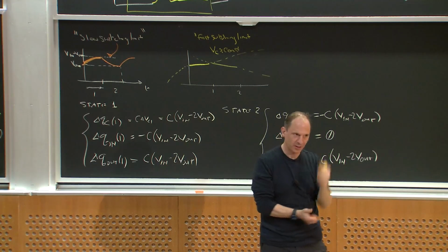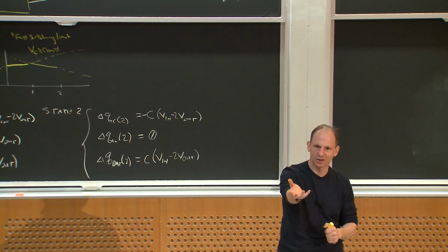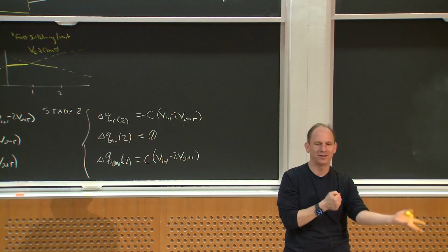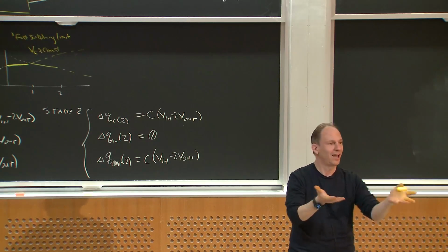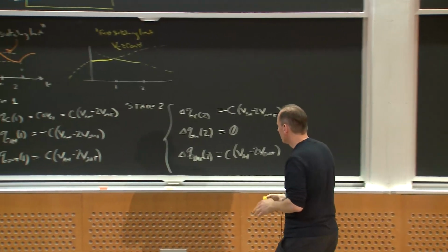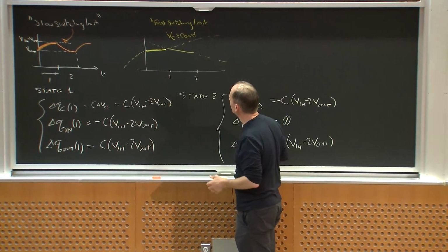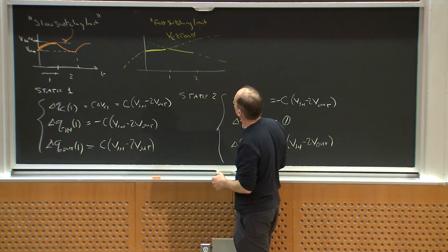But it's a special constant voltage because, if I'm going to be in periodic steady state, however much it charges in the first state must balance the amount it discharges in the second state, right? I haven't gotten around that kind of rule. But nonetheless, we can think about this fast switching limit as the capacitor voltage almost becoming constant.